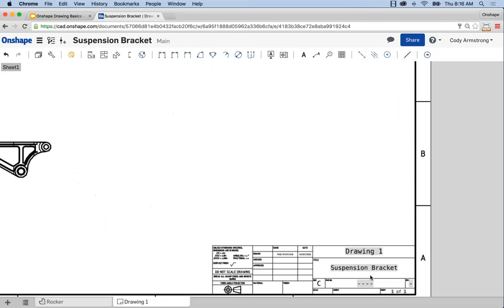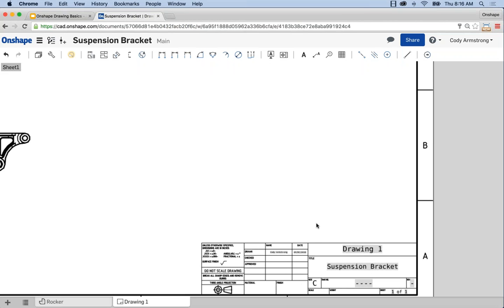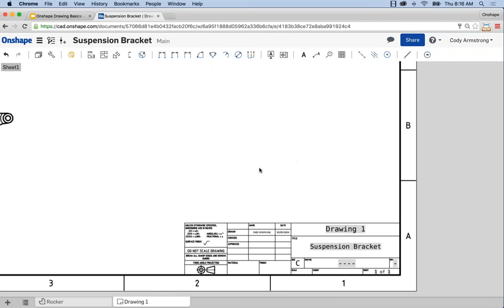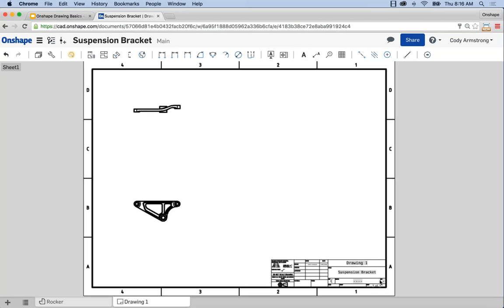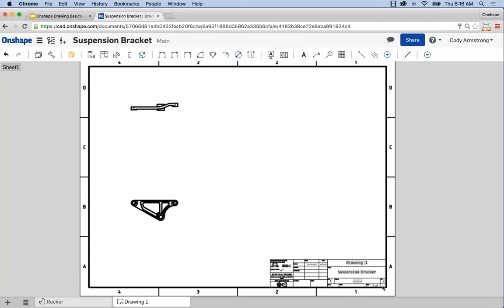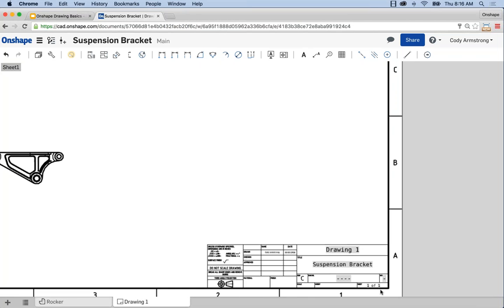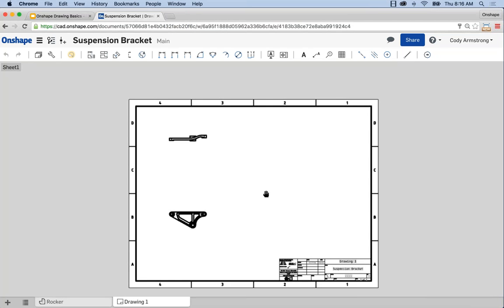You can fill out the title block. Forgive me if I'm not answering the question correctly here, but you can fill out the title block with properties stored within the drawing. So right click and select properties. Keep in mind though that this is something we hope to expand to a much greater degree in the near future. Right now, you're still filling out a series of properties associated with it, and it populates the title block. Some neat things though, like the sheet number, for instance, are automatically recognized. So when you create a new sheet, it'll become one of two, for example.